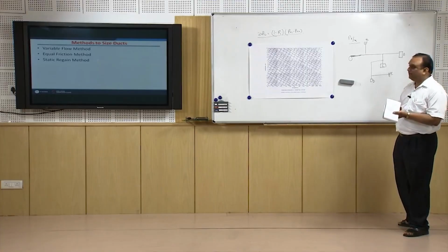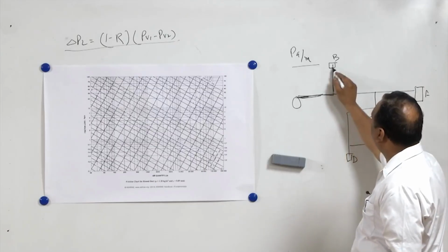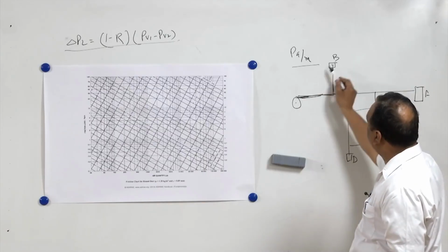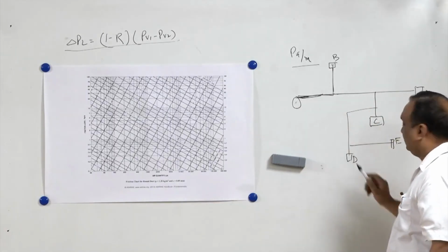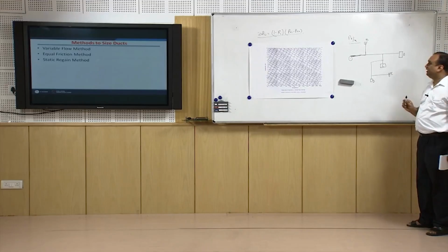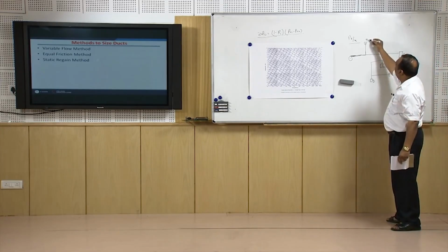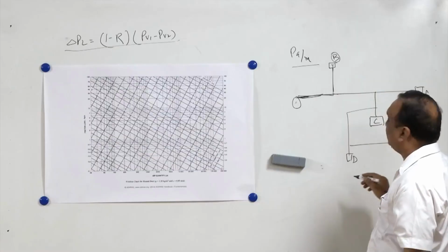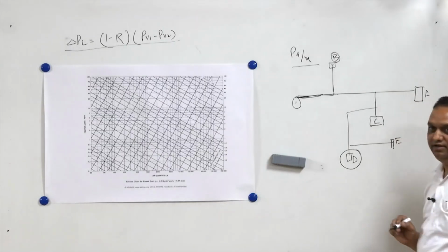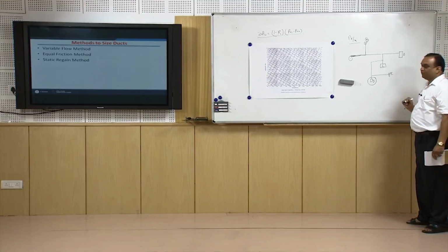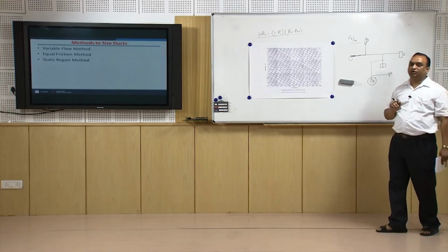Now here what happens, suppose you take this discharge from here, so the absolute pressure drop in Pascal between these two points will be less than the pressure drop between this and the farthest point. So in that case there is an imbalance of airflow, and it is possible that airflow from B is much higher than the required value and we do not get any airflow at the D outlet. So in order to control this, dampers are provided at all the openings.